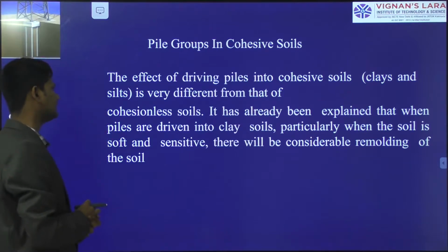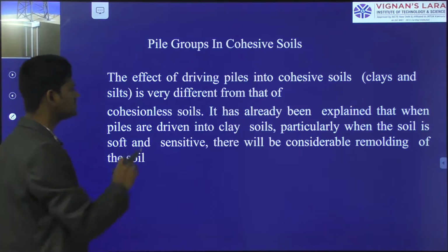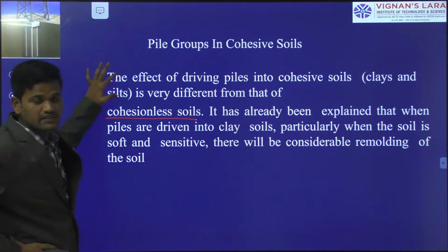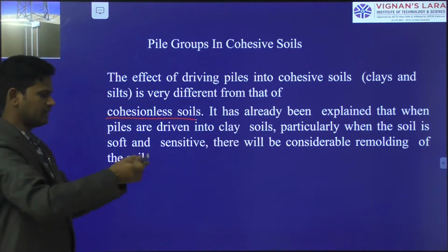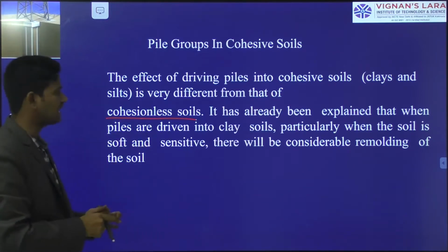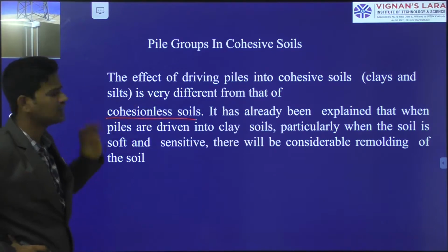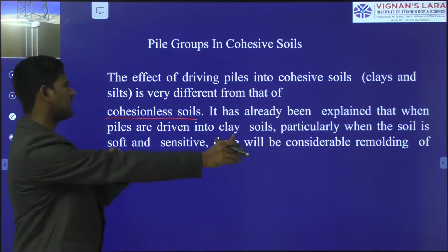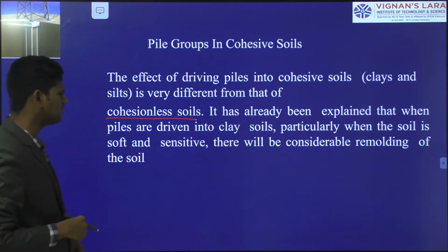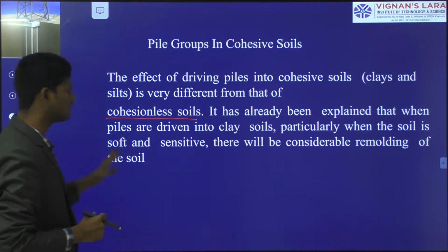If you come to here, the effect of driving piles into cohesionless soils is very different from that of clays and silts. That means while you are driving, by hitting action and driving action into the soil mass, inserting the piles into cohesionless soil may behave differently from cohesive soil. It has already been explained that when piles are driven into clay soils, particularly when the soil is soft and sensitive, there will be considerable remolding of the soil mass.